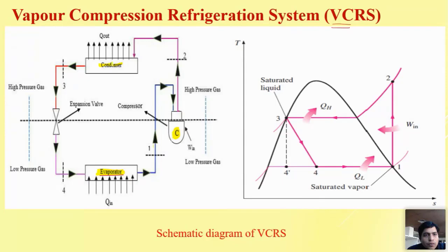In the condenser, we want to lose heat to the environment. This heat normally should be in terms of latent heat only, but we want to reduce the sensible heat also, so that the work for the expansion valve reduces, and later a very small amount of work needs to be done with the help of the expansion valve, which is actually not very small, because the temperature and pressure both decrease during the expansion here. This follows the concept of the Joule-Kelvin effect, probably you all know that. And then it goes back to the evaporator.